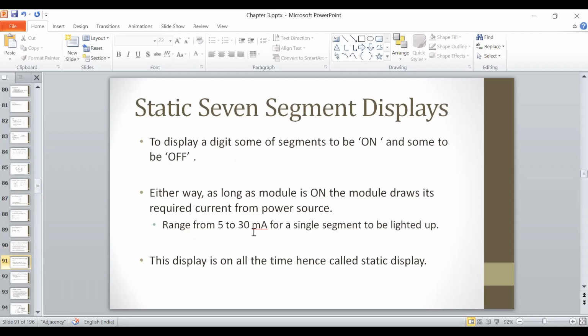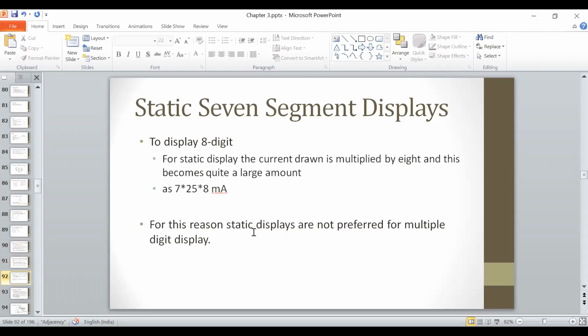नीड 8 7 सेगमेंट एलईडीज, ठीक है। तो दिस इज व्हाट द गिवन ईयर कि अगर हम एक 8 डिजिट डेटा को डिस्प्ले कर रहे हैं तो हमें 7 सेगमेंट एलईडीज कितने चाहिए होंगे, 8 7 सेगमेंट एलईडीज चाहिए होंगे। सपोज एक सेगमेंट, इस 7 सेगमेंट एलईडी के एक सेगमेंट को डिस्प्ले करने के लिए हमें कितना पावर चाहिए, 25 मिली एम्पर। तो टोटल पावर आपका कितना हो जाएगा, 1.4 एम्पियर के अप्रोक्सीमेट हो जाएगा, विच इज अ वेरी हाई